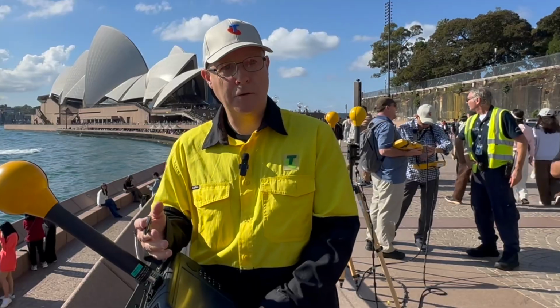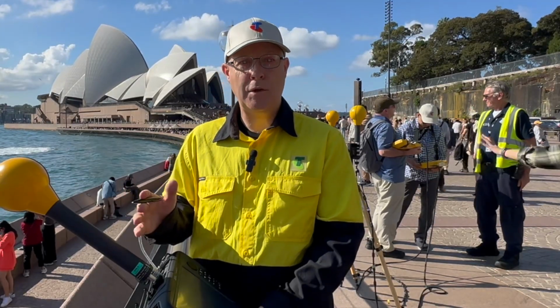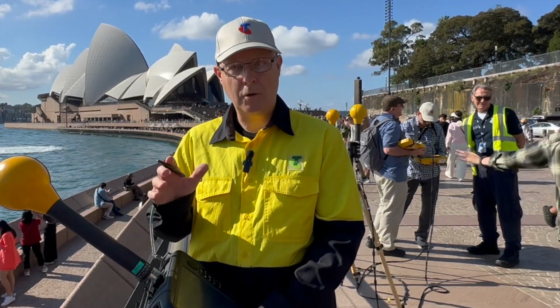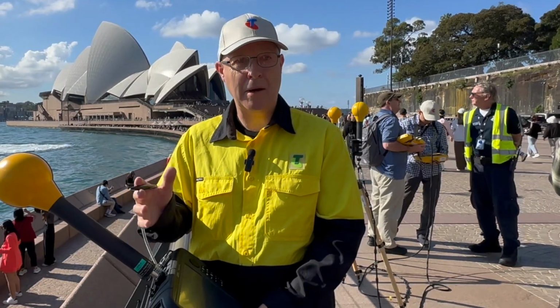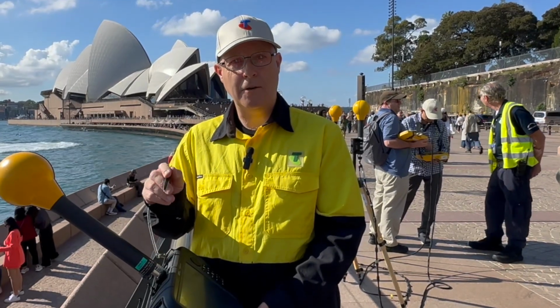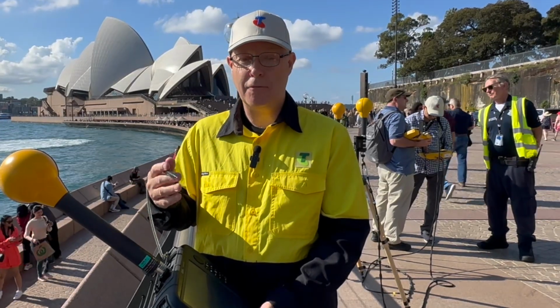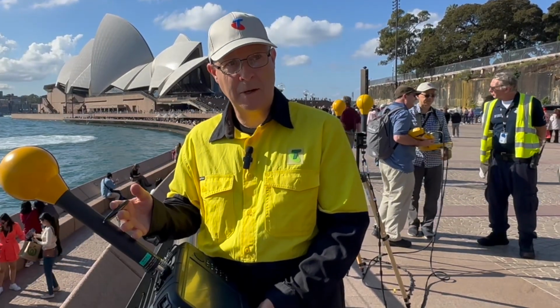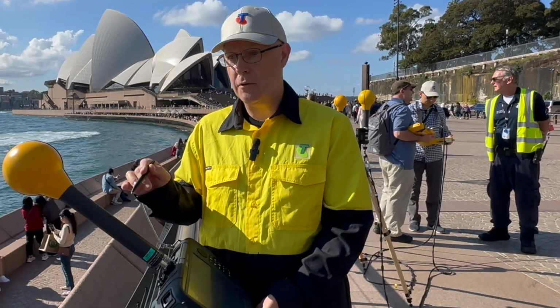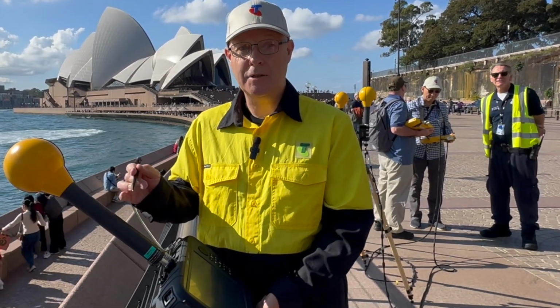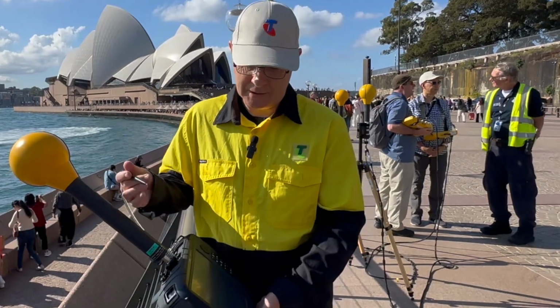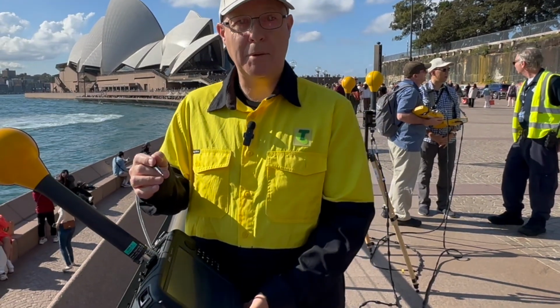That's one set of readings that we want to do. And that's a very useful setup because that captures everything in one go, and we can look at the channel power and integrate over the band. Or we can go into the 5G Analyser mode and look at the individual network operators. So from our perspective, we can go and choose the Telstra band and look at the actual radio frequencies extrapolated for Telstra at this location. So there's two options. So I'm going to show you the extrapolation mode first.